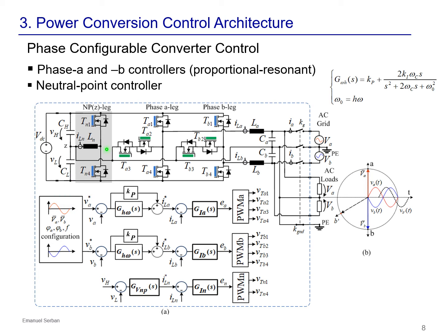In fact, the voltage across them is balanced by this leg, and this inductor can be designed at a much lower size than the phase inductors LA and LB. Therefore, smaller overall size and lower design cost.